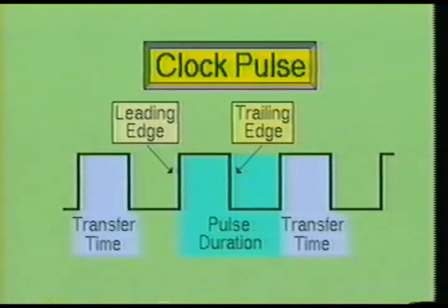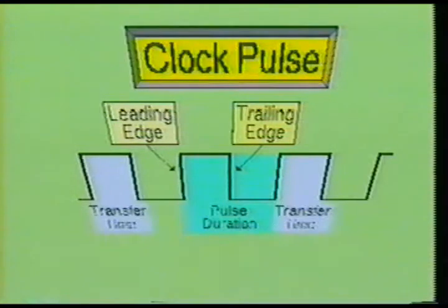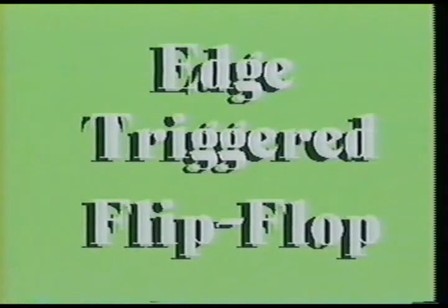In the various flip-flops shown thus far, the control inputs are effective during the interval that starts at the leading edge of each clock pulse and ends at the trailing edge of the clock pulse. However, there are times when the inputs must only be effective for a short interval of the clock pulse duration. In such a situation, the edge-triggered flip-flop satisfies this need.